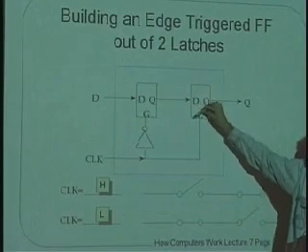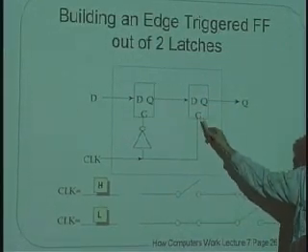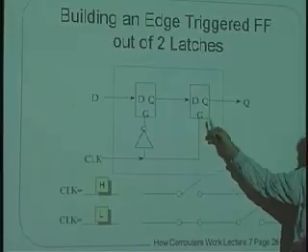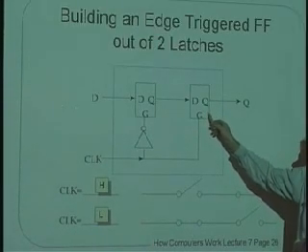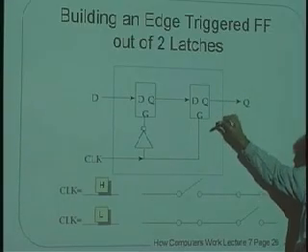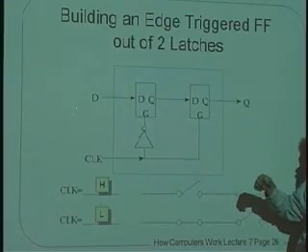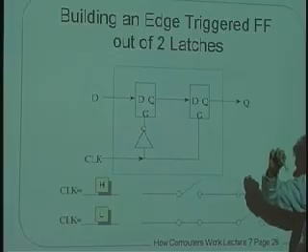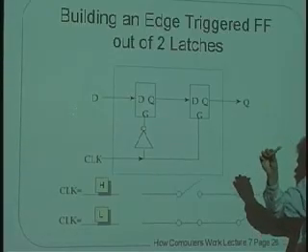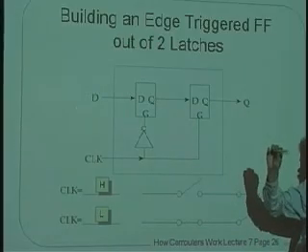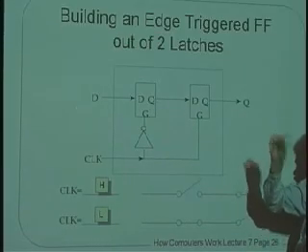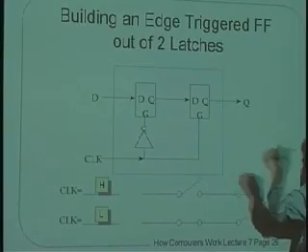Okay, so what these circuits do when we're in the intermediate state where both G's are off is that they hold on to the old value there because they themselves are memory elements. A selector is not a memory element. So when you're halfway between one switch setting and the other, it doesn't know what to output. So what we're saying is that if you are halfway in between the two settings and both of the inputs are the same, output whatever that input is.